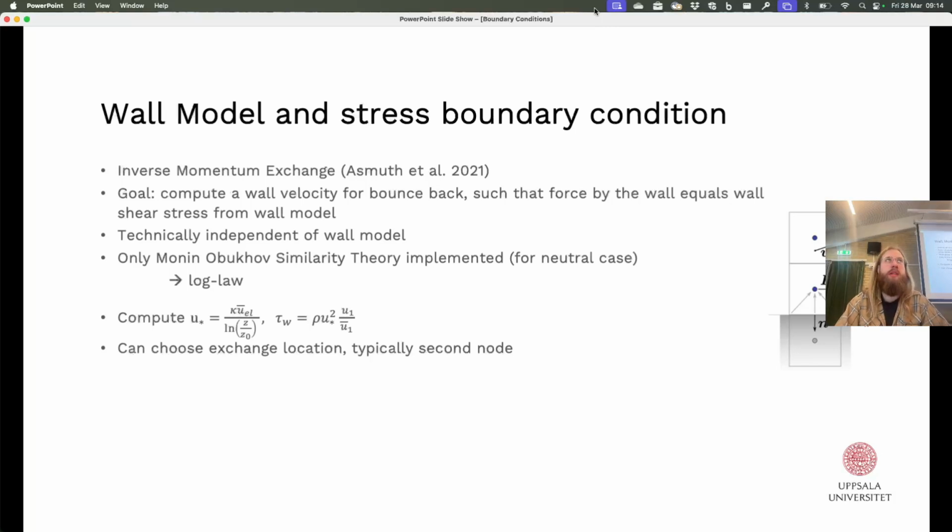Okay. So the theory is, in general, you have to decouple the computation of the wall shear stress from the instantaneous velocity at the first node somehow. And there you can do it by spatial averaging, or by temporal averaging, or also by not putting the exchange location at the first node. And we just combined two approaches; we picked the second node. I think this comes from the Palm people. I think they introduced this, that you use the second node and not the first node.